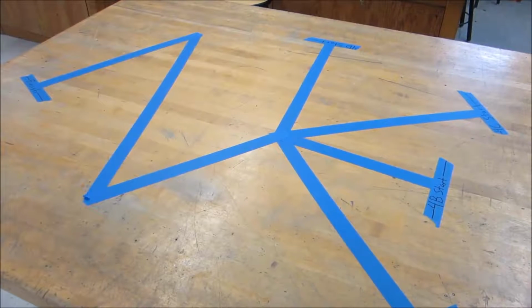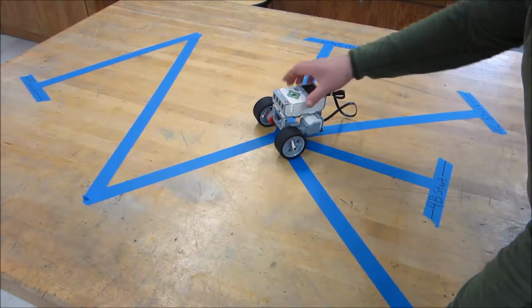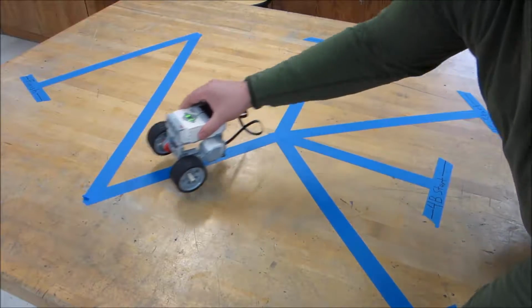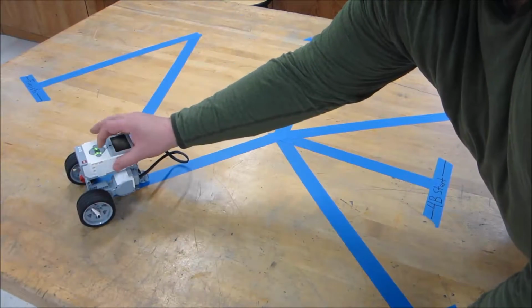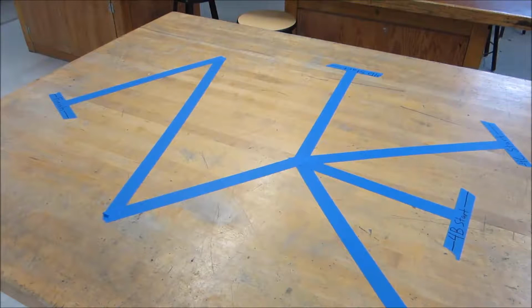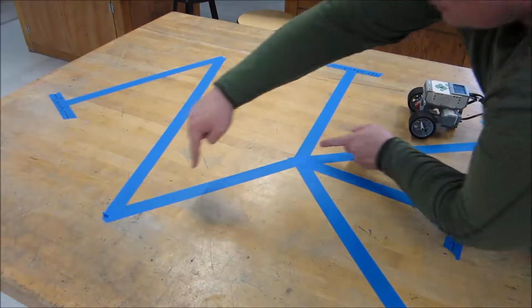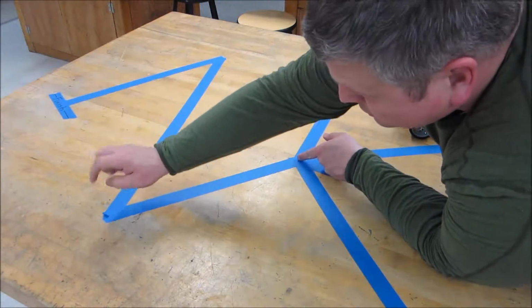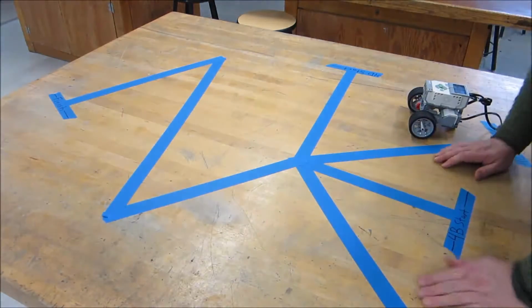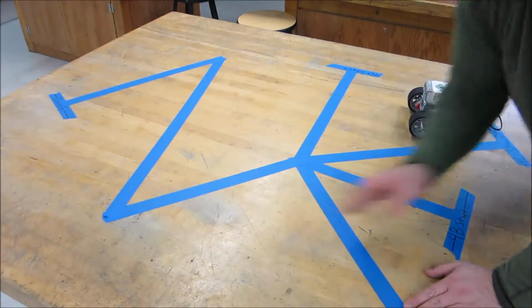So now the next phase, we're going to put in another weight block now that we have our turn right, and then we're going to tune it to go exactly this distance. Before we go back and do that next one, it's important to notice that this distance here and this distance are almost the same. It's just this one's a little bit longer. So we can use kind of our success in the past here to get this one tuned up correctly.